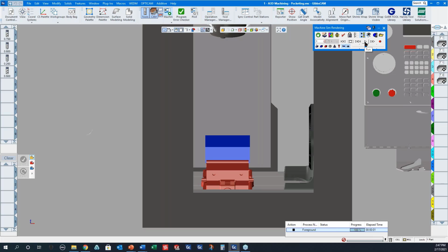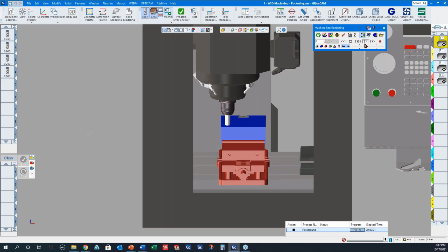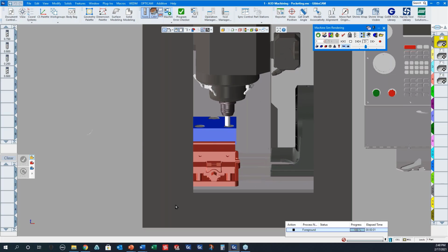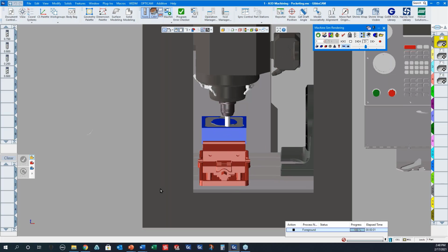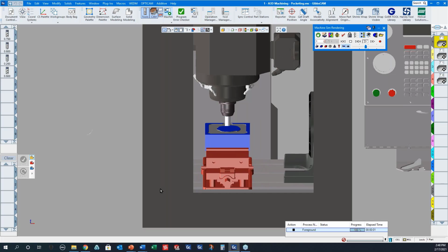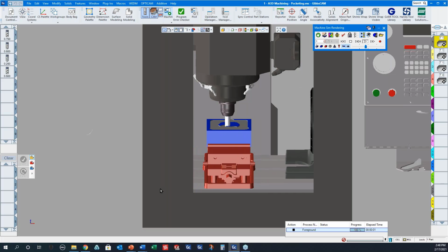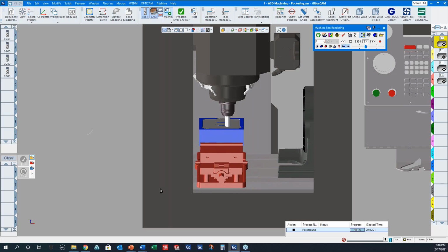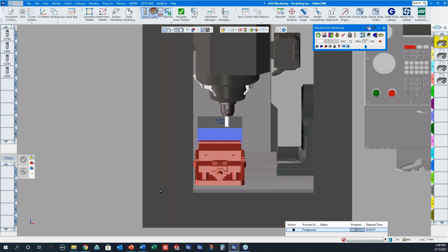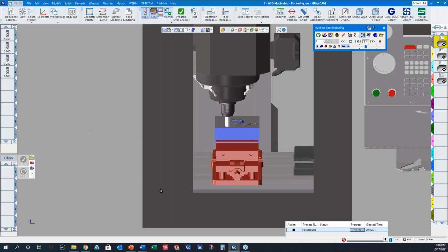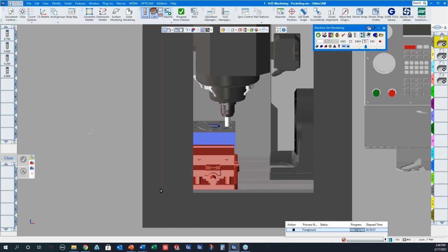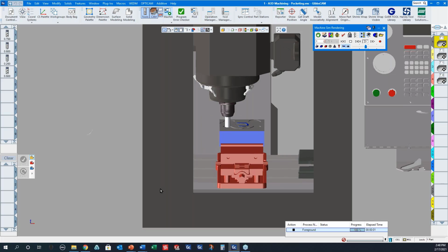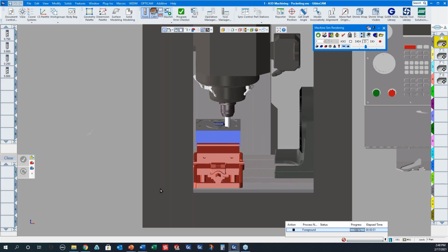The first one we have is, what tool types does advanced 3D machining support? Because advanced 3D machining toolpaths are designed specifically for cutting molds, it only supports flat bottom, bull nose tools, and ball nose tools. And it will always be gouge-free toolpaths. So those are the only three tool types that it supports: flat, bull, and ball. If you need additional support, like being able to undercut things or use other types of tools, we recommend moving up to the 5-axis module.